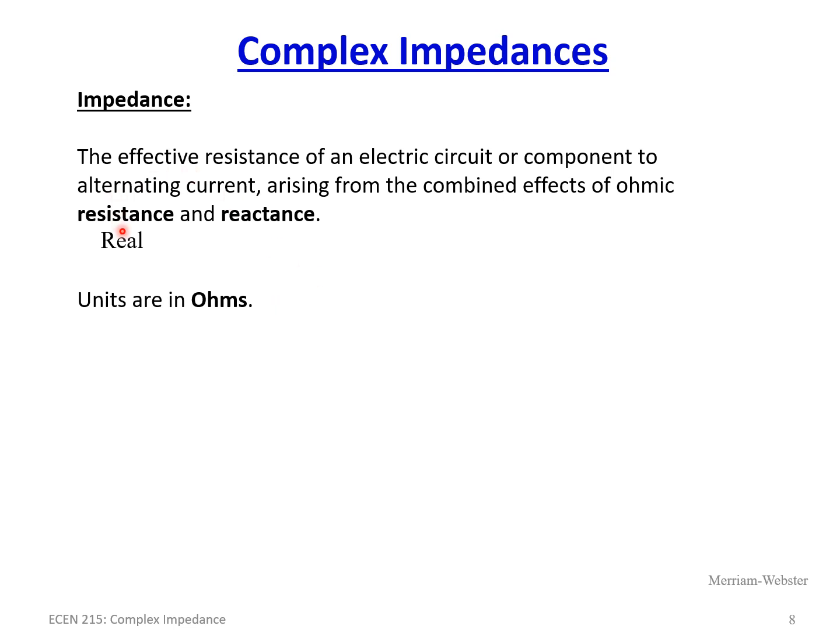Again, the resistance is the real component and the reactance is the imaginary component. Ohm's law still applies, but we have now changed R, so we don't get it confused with the real component resistance, to the letter Z. So Ohm's law stays exactly the same. V over I is equal to Z, V over Z is equal to I, and V is equal to I times Z. Everything stayed exactly the same linear relationship. Instead of R equal to V over I, we're now saying Z is equal to V over I. Of course, these are all in phasor terms.